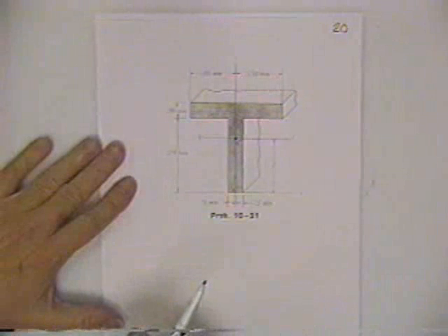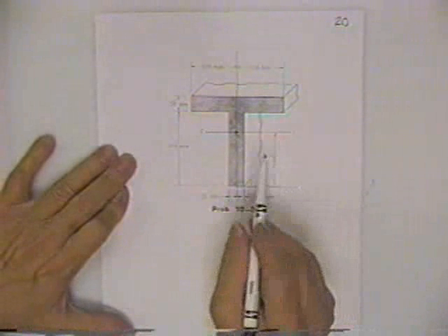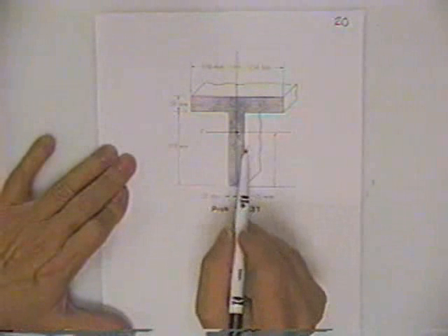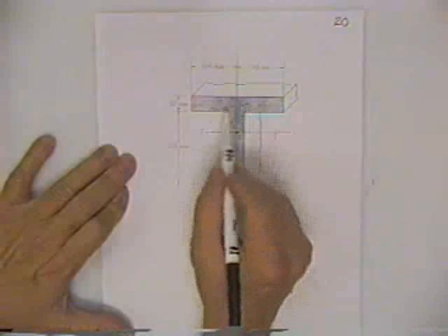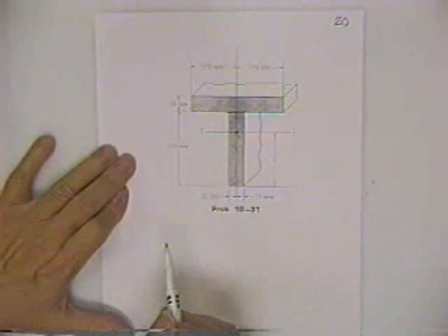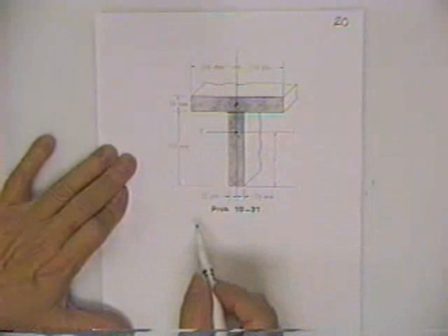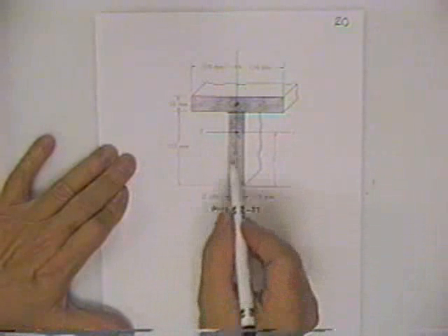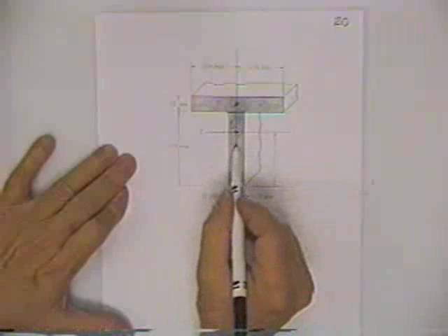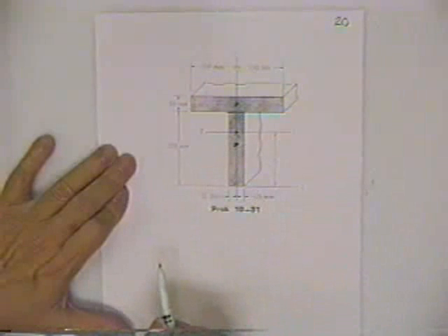All right. Centroids of plane areas use about the same idea. First, in order to find the centroid of a strange looking piece like this would be to break it up into pieces that don't look so strange. Break it up into a solid rectangle that you totally understand how big it is and where his centroid is, and divide it up into a rectangle whose centroid you know where that is. And of course the centroid of a rectangle is in the middle, halfway.